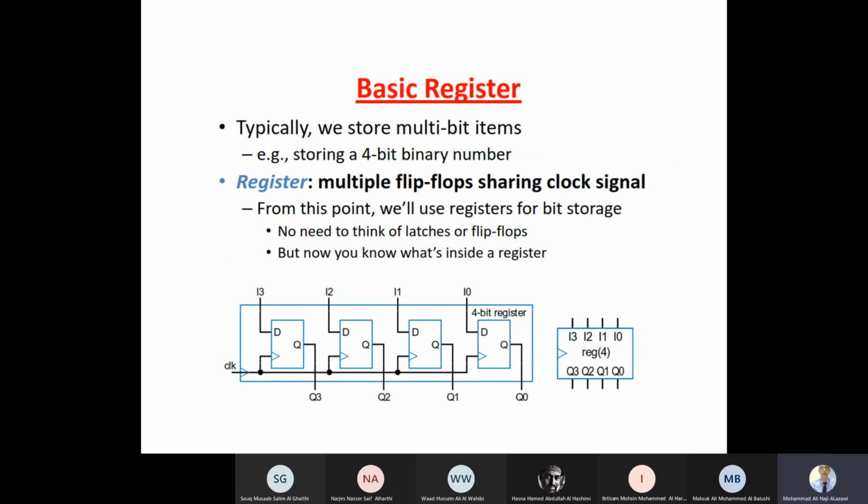Okay, very well. Now we have an example, an application about registers. When you hear the word register, that means 100% I'm talking about D flip-flop. Of course, D flip-flop or JK or SR, because both of them can be used as D flip-flop, correct? If I use SR, then I can convert them to D flip-flop like this. In all cases, the word register means a place where I can store a bit for a while. Then I'll certainly use the D flip-flop. You cannot use T flip-flop for registers. Why? Because the T flip-flop toggles, or inverts, the input. So register means D flip-flop.